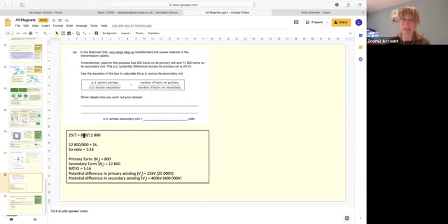That is what I mean when I talk about a ratio. You work out that it is 16 times bigger by doing this bit here. So the ratio is 1 to 16. If I have 25 in this one, I have to have 400 kilovolts, or 400,000 volts, in this one here.